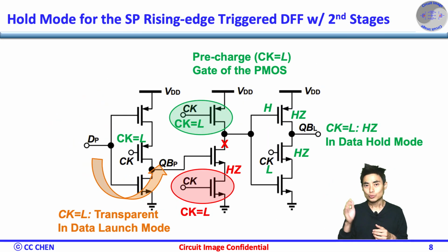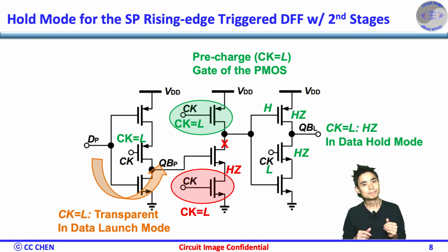Good. We need to pre-charge the gate of the PMOS to be high, such that the last stage output will be high Z, PMOS off as well. So the CK is tied to the PMOS gate at the second stage. To make sure the pre-charge activity doesn't mess up, the CK clocking should get off the NMOS as well.